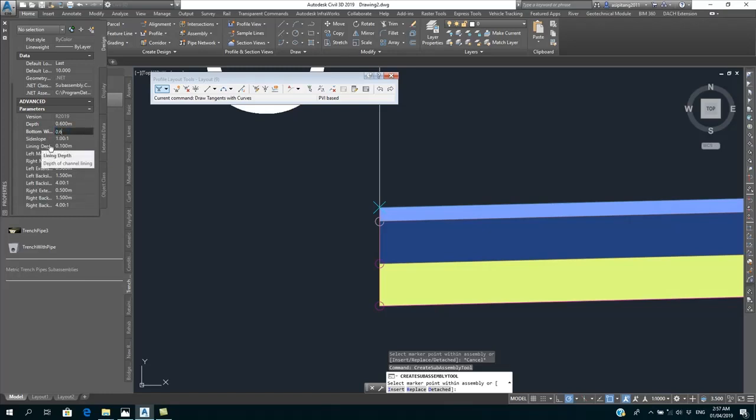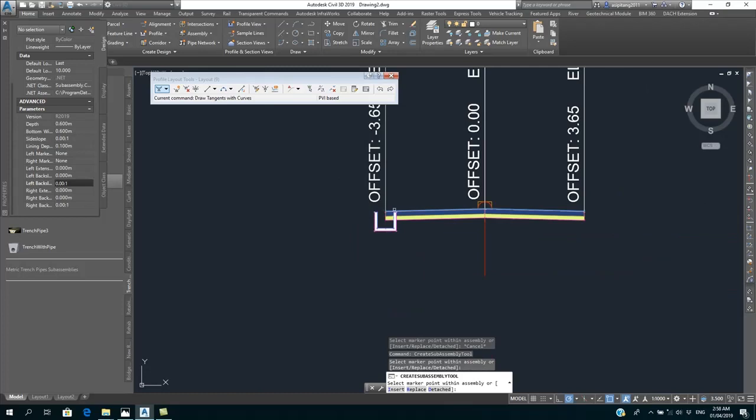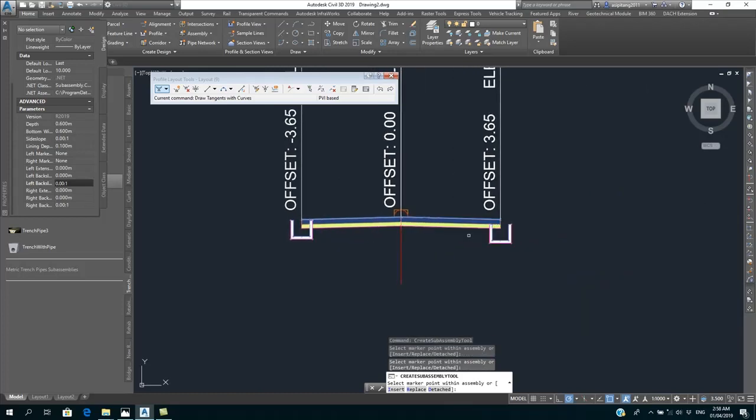These are end-to-end information descriptions. The side slope for a U channel is 0. The lining depth, that is the thickness of the walls, is 100 mm as used. Then, because I don't have this in a build-out area, I don't have any kind of offset from any direction for a build-out street road. So it just terminates at the drainage, all information refers to it. So I get the information and put it where I want to locate it. Other times I put it as such too. So I have the drainage.